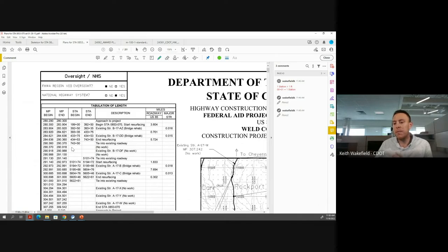The best way, really, in my opinion, to tie everything down, to make sure something's at a specific location, is to relate it to benchmarks or property pins or something that's actually surveyed in there and shouldn't move around. Whereas I think a milepost is something that is more arbitrary than a benchmark would be.